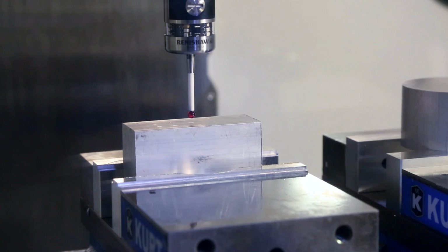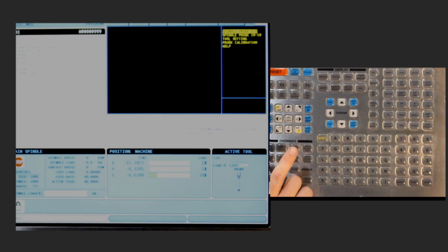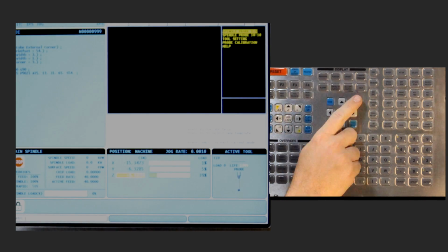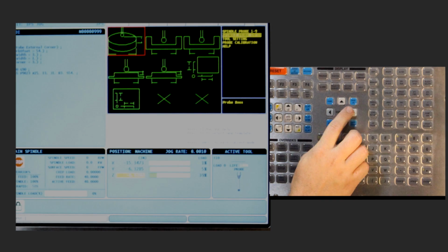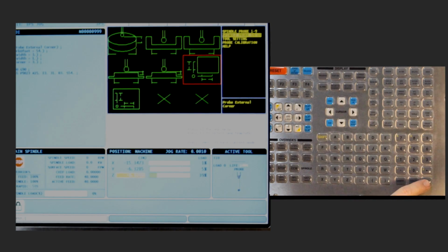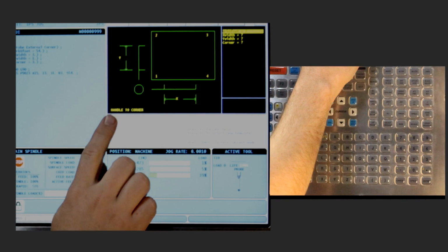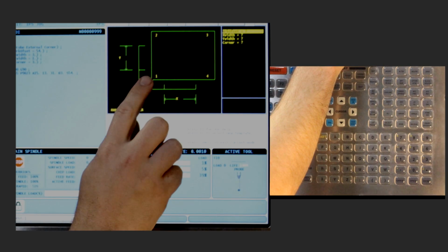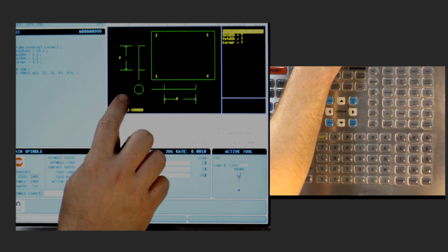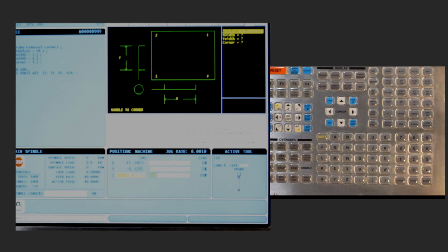After checking our inputs, we'll take a look in the machine and notice we have not yet moved the probe into the correct position to begin this routine. We can go back into VQC to reference the visual graphic. Notice, the probe needs to be moved away from the corner so that it will not contact the sides when moving parallel to them. Let's jog into position.